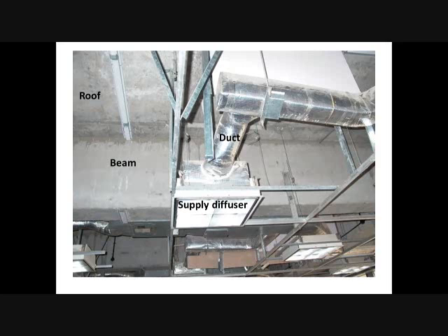Another question, what's the diameter of the ducts? We have another slide that shows the diameters and sizes. At the last diffuser, this is the minimum, 20 by 30, something like this. But when you have two sub diffusers, then the duct between them will be, for example, 30 by 30. Then it starts 30 by 40 and 40 by 40, so you understand that it carries the volume of air that is required for each room. So I will show you a diagram now that has the dimensions.